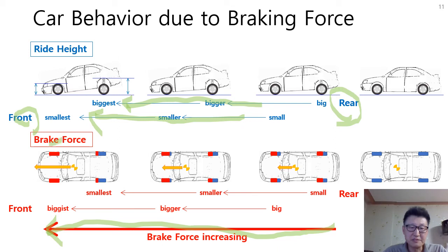Brake forces at the rear wheels decrease bit by bit in this direction, while those at the front wheels increase bit by bit in this direction, in proportion to the quantity of transferred weight. Let's investigate what happened at the rear wheel in the braking. The higher CG height results in a series of undesirable effects that make the car performance deteriorate. The bigger the weight transfer, the higher the ride height, and the weaker the tire grip, which cannot produce the stable brake forces at the rear wheels.